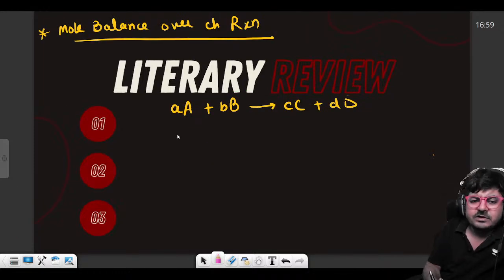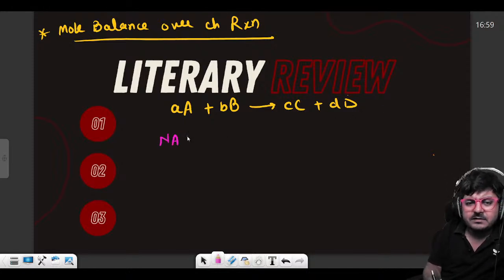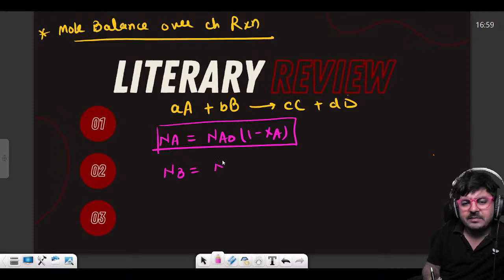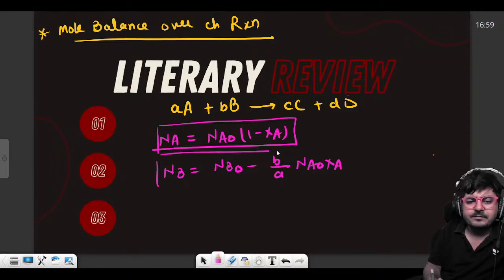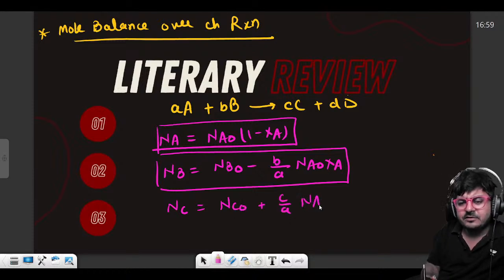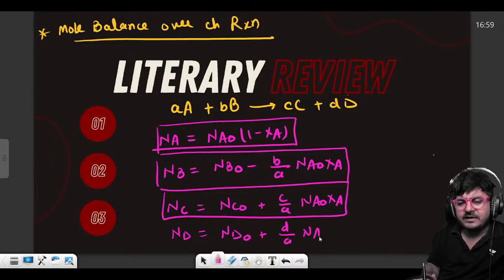Okay. तो यहाँ पे आते हैं. तो यहाँ पे अगर आपको A के लिए लिखना है, see everything if you have to do in terms of XA, so you can write moles of A remaining Na is equal to Na0 1 minus XA. If you guys remember, these were the mole balance equation. इनका हम derivation यहाँ नहीं कर रहे, उसका कोई ऐसा मतलब नहीं है. For B, you can write them as NB0 minus B upon A times of Na0 into XA. Similarly, moles of C formed or leaving the reactor can be written as NC0 plus C upon A times of Na0 into XA. And for D, you can write ND as ND0 plus D upon A times of Na0 into XA.